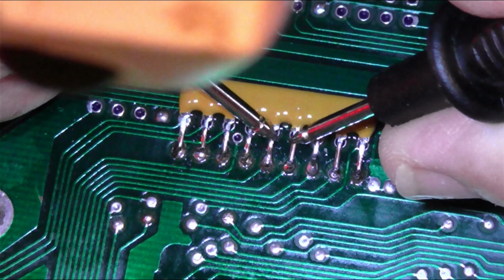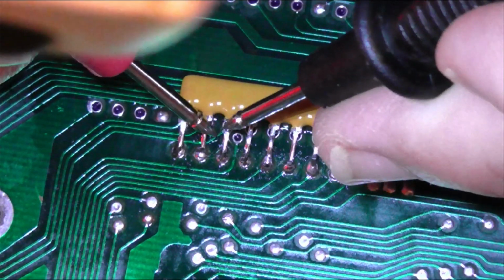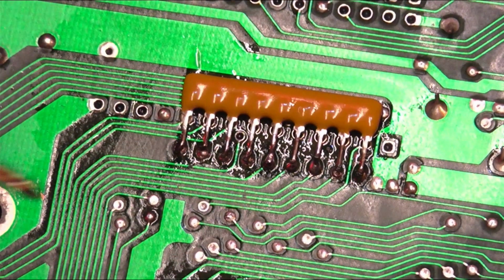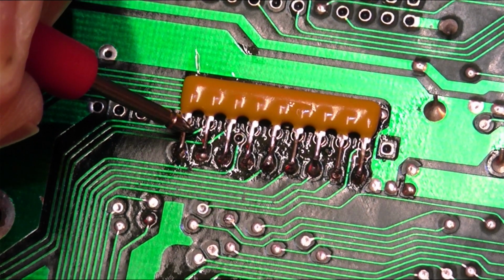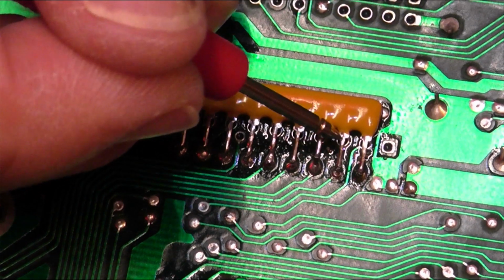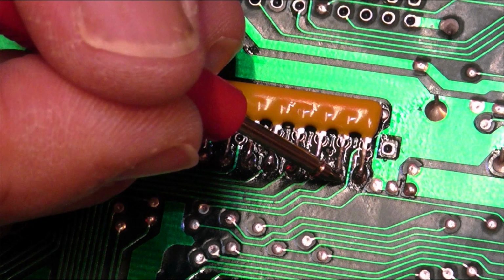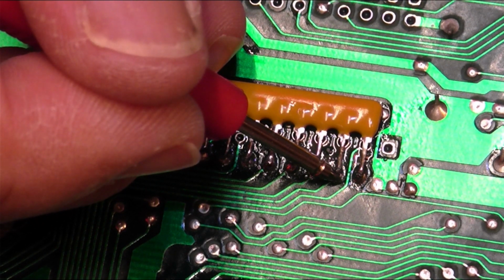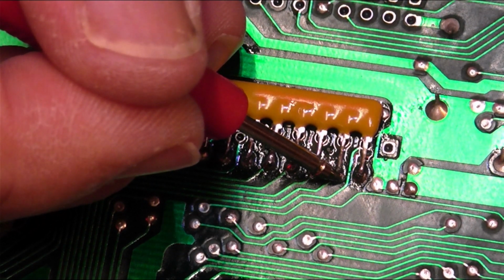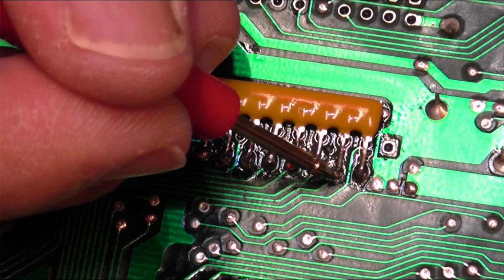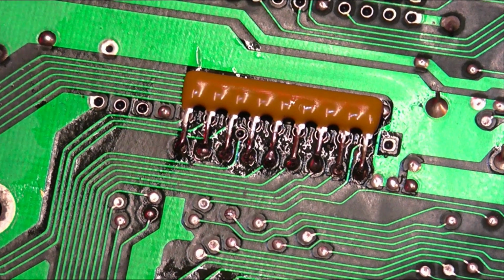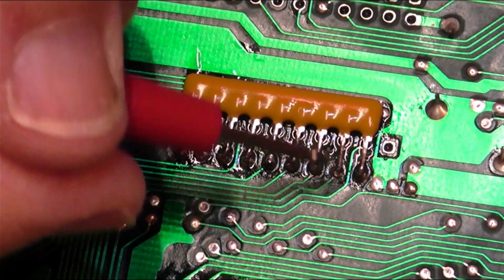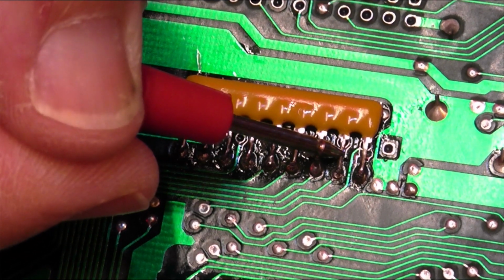Just firstly checking for shorts, and then we're going to check if we have continuity between each pin and somewhere on the 68K. This pin here is the one that looks dodgy. Yep, so that's got connection to, I think that must be A5, 6, 7, 8. I'm guessing that's A8. So that pin is A8, but our resistor